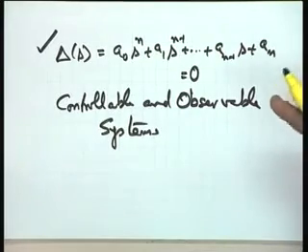So, as far as the answer on absolute stability is concerned, probably we should not continue with our discussion, because computer aided software is available today to answer the question. In every lab you are equipped with computer software, so that you give this polynomial as an input, it will give you the roots of the equation, you examine the roots vis-a-vis the S plane and give your conclusion about stability.